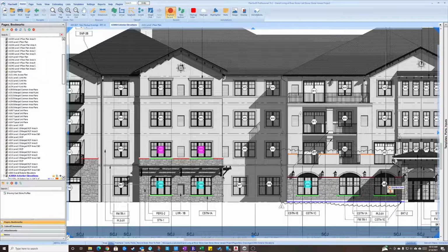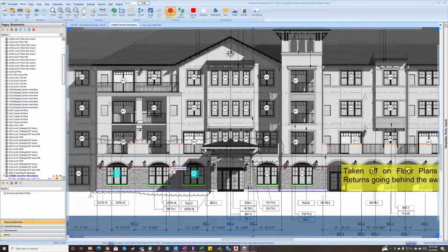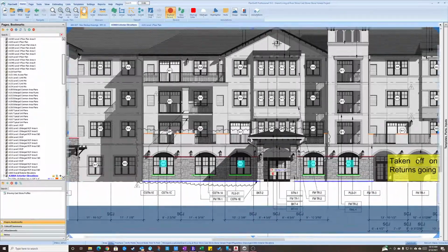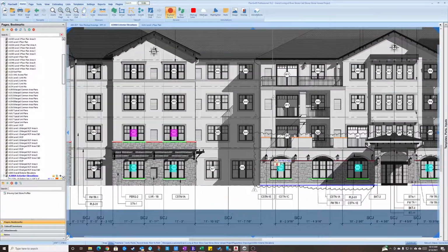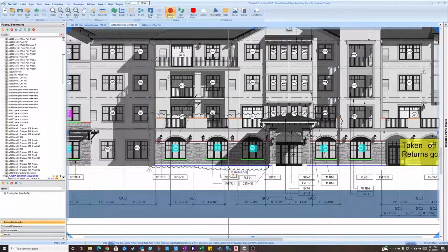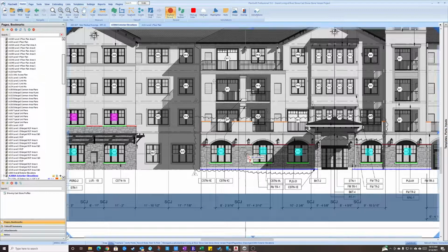It looks like we have a few more W8s than the other ones. Looks to me like this is also a W8. It's just not marked with a W8, so you have to be careful about that. Sometimes the architect will accidentally skip over some stuff. It looks identical, it's just not labeled. So it's your responsibility to click it and make sure we're counting it.